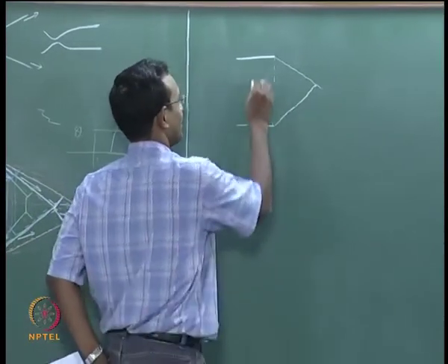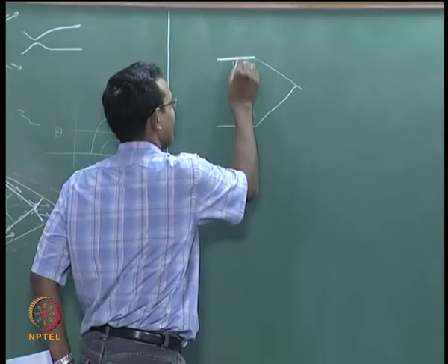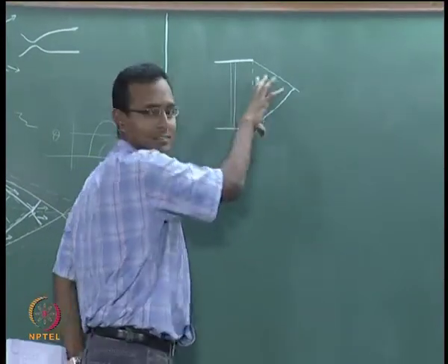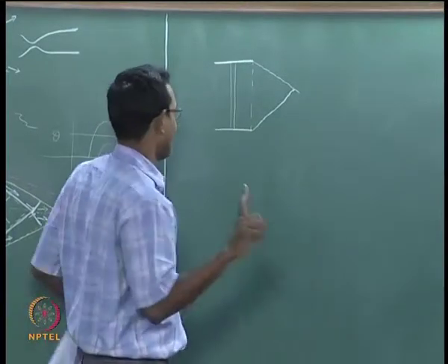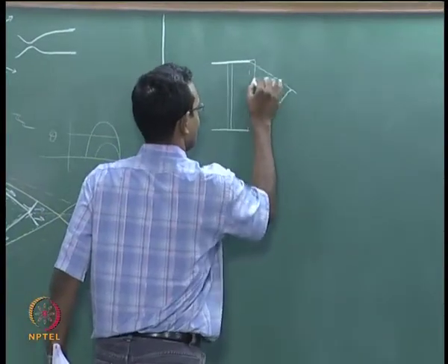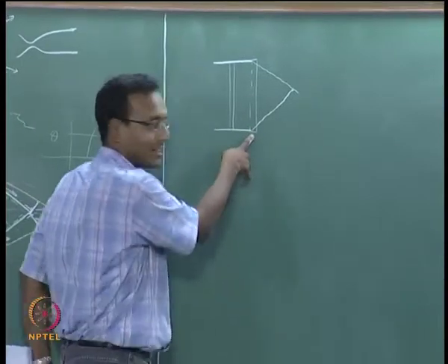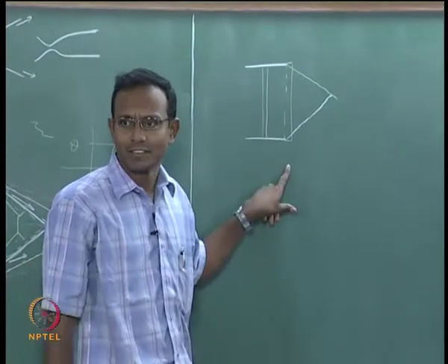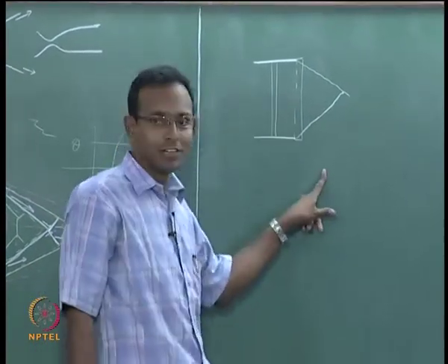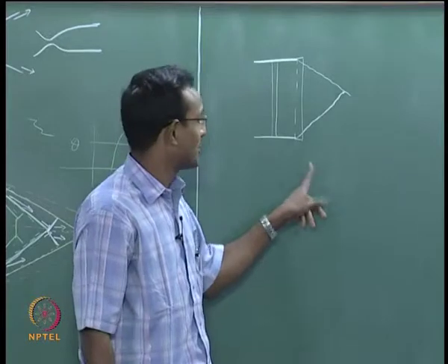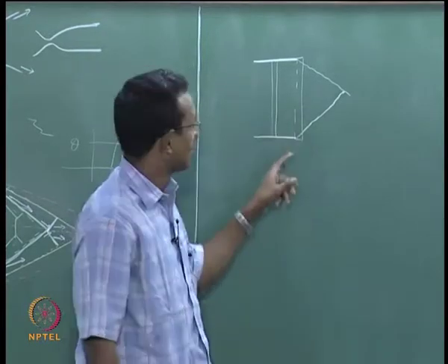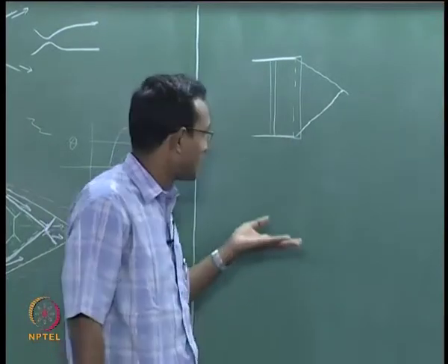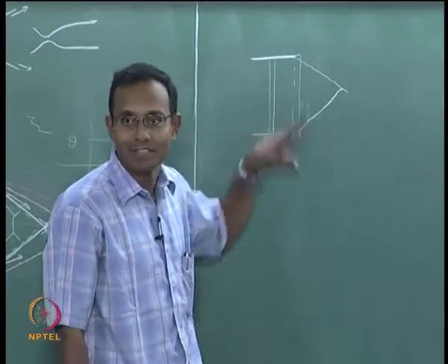Currently what is going to happen is there is a slab of fluid, it is coming with some reasonable velocity, and suddenly when the slab comes to the exit, this corner is seeing higher pressure. Why higher pressure? It is an over expanded jet, this is over expanded compared to the outside world. Okay. So this pressure is higher than this inside, so it is seeing a higher pressure. What is it? It is suddenly pushing, like a piston suddenly pushing against the fluid slab there.